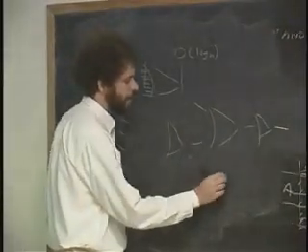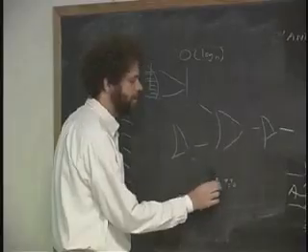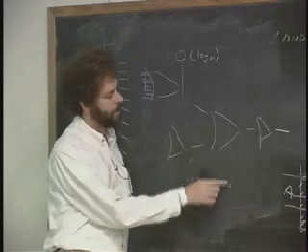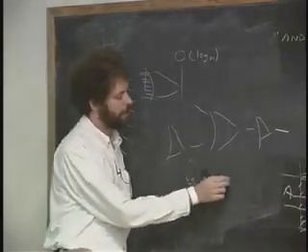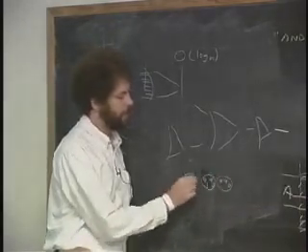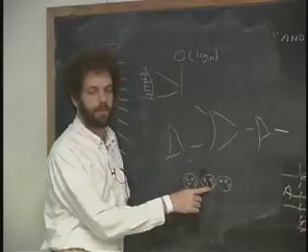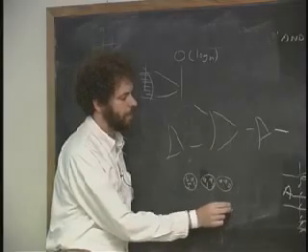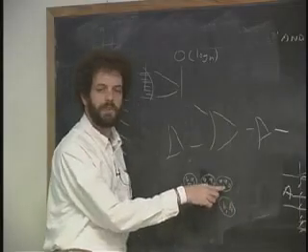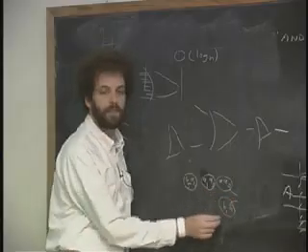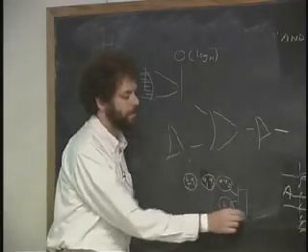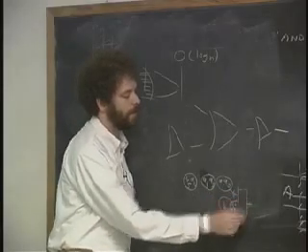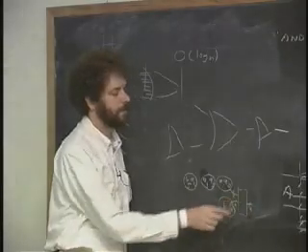So here's a sub 0, a sub 1, a sub 2, a sub 3, a sub 4, a sub 5. Rather than treating each one of these bits the way we've been doing now, treat them as little groups. So here's a number between 0 and 3. Here's a number between 0 and 3. And instead of adding this bit with bit b sub 0 and b sub 1, we're going to add the number between 0 and 3 to another number between 0 and 3. Worst case, we'll put it into a lookup table. There's 2 bits here, there's 2 bits here. We can do this pretty fast, and we can get two bits out here that's a little bit faster.